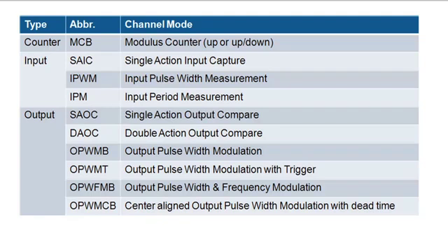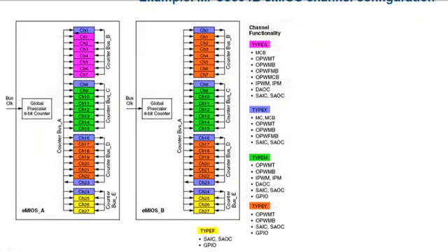So basically every time your counter reaches, let's say, a value of 100, you can turn on or off current to a motor, but you can also have, when it gets to 100, a dead time, either going up or going down, to allow for, like, an H bridge. Okay, we'll look at a few of those that I think you'll need later, but once again, not every eMIOS channel has all of the functions.